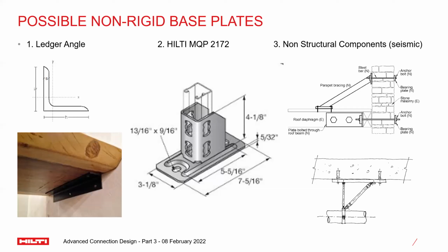When you do an anchor design on any of these, these are just examples. There are many cases. It doesn't always have to be thin. The concept of thin is based on the loads that you're applying on your base plate, right? So 4 millimeters can be thin for, I don't know, 1 ton of tension force, but 40 millimeters can be thin for, I don't know, 100 tons of tension. I'm just making the numbers up, but you understand what I mean from the examples. These are all examples where a rigid assumption may not predict the true behavior of the base plates under applied loads. Here is where finite element methodology based base plate design checks will yield a more realistic behavior.